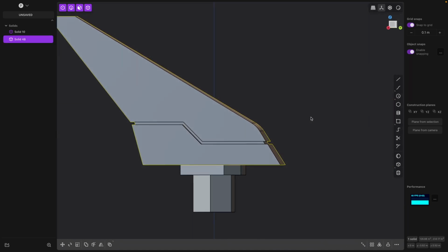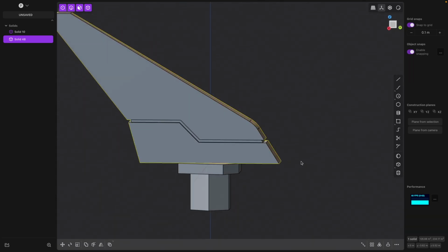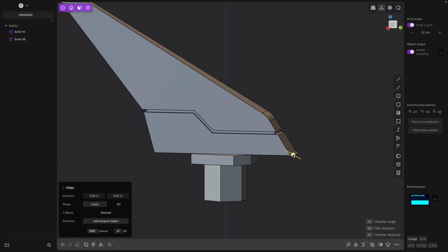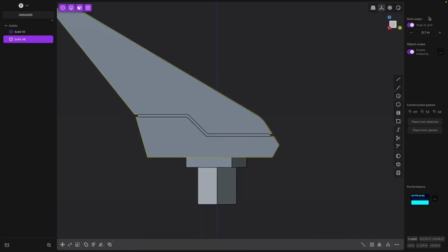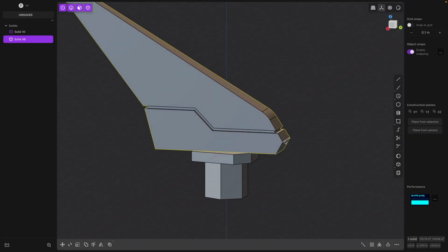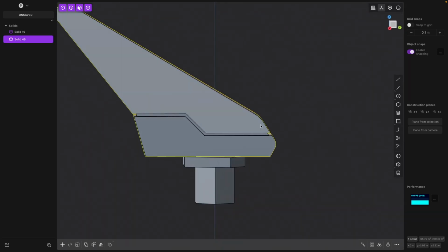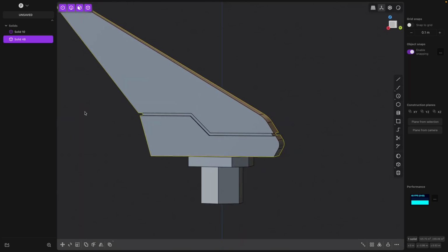I want to actually add some sort of rounded curviness to this shape, right? So that's a nice thing to do here in Plasticity: once you get your basic shape, you can embellish it and make it much more interesting. I don't want that to curve, I want it to be flat like this. I'm going to turn snapping to the grid off because I noticed as I was dragging that it was locking me at certain locations. I'm going to put a curve on this one. So yeah, now our leading edge is a little nicer.